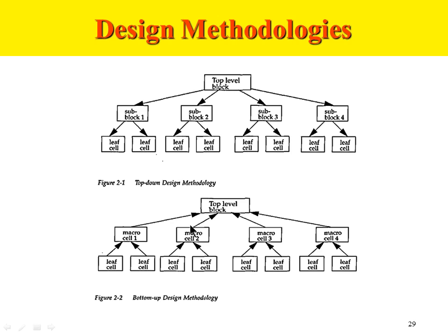So forget the verification for now. The design can be done this way: a hierarchical design can be done bottom up or top down. It is very common that this is broken down into steps, and one engineer of the team might get assigned to develop a block. He or she has to write Verilog code for it and a separate test bench, verify the block, and then hand it over to the sub block level. That's how hierarchical designs are developed in Verilog, which is extremely common.